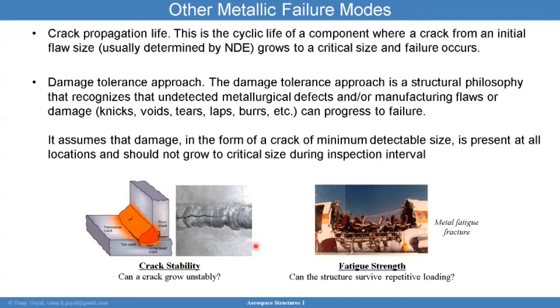Here in the bottom left, I have an example of a crack in the weld area, or a root crack, or a crack in the heat affected zone, also what we call a toe crack. Well, these cracks may not be detectable by the NDE, the non-destructive evaluation techniques that are typically used for detecting this kind of damage.